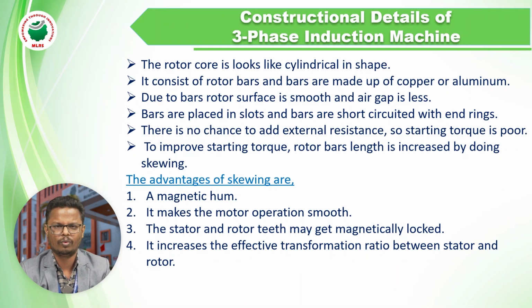And wherever we require constant speed applications, that is, even though the load increases, the speed should not change over a wide range, there we can use these squirrel cage induction motors. Mostly in 90% of applications we are using squirrel cage induction motors compared to slip ring induction motors.